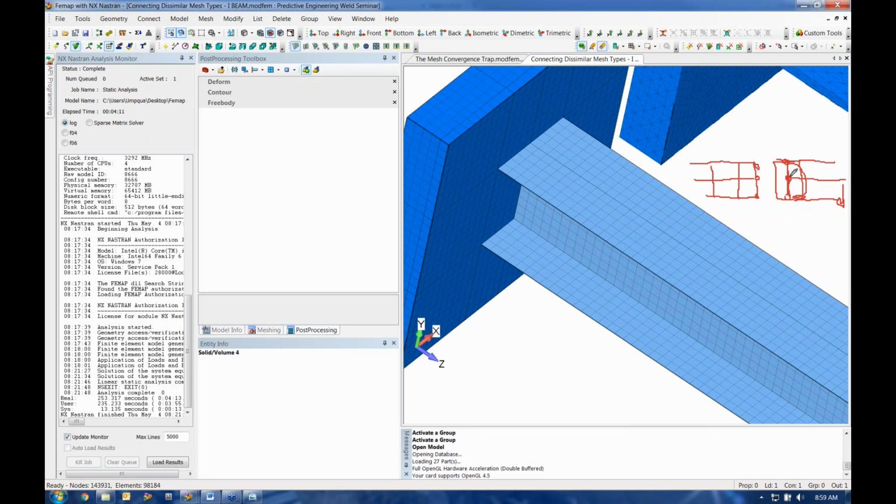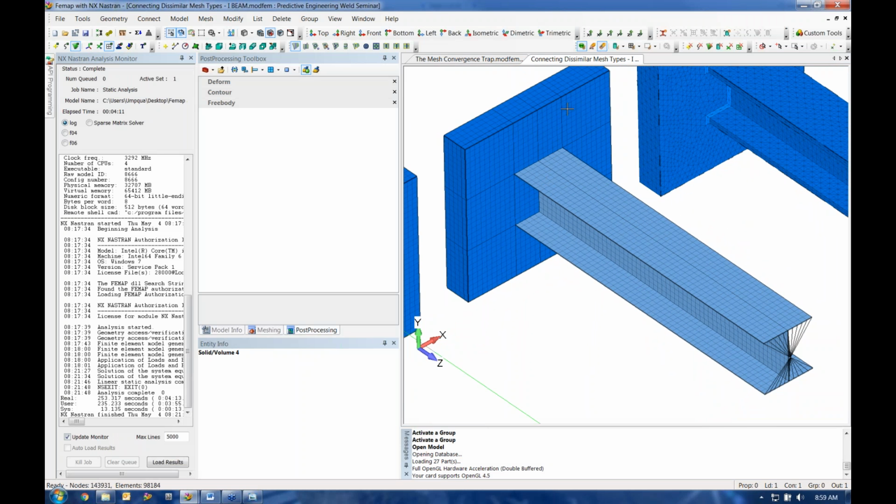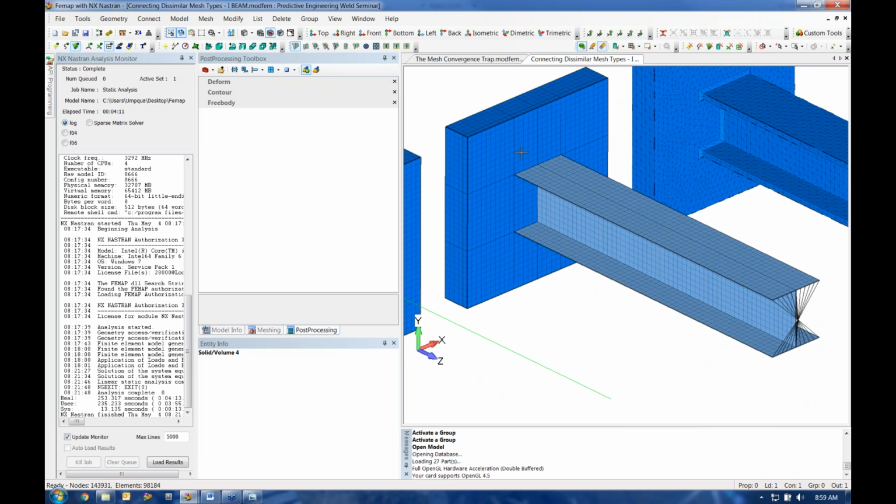Now, again, this requires quite a bit of setup work and is not always the most useful way to use your time. So again, this is something where glued connections might be the way to go. Just like we glued plate edge to plate surface, you can also glue plate edge to solid element surface. We saw before that it does a great job of capturing the stiffness values, incorporating the thickness of our elements. And so it could be easier to set up and more accurate in terms of your actual stiffness and load transfer.